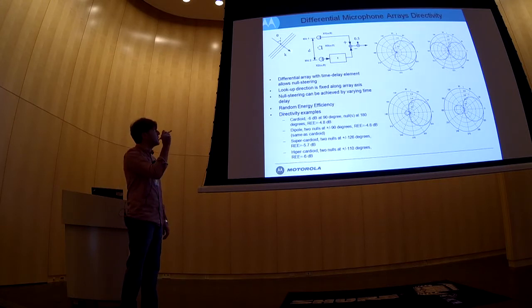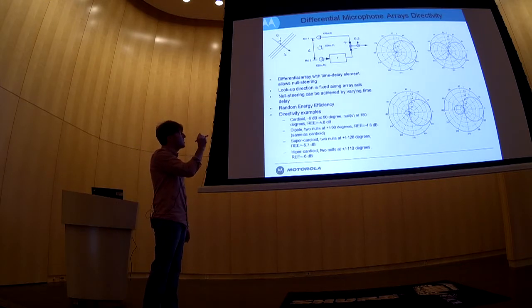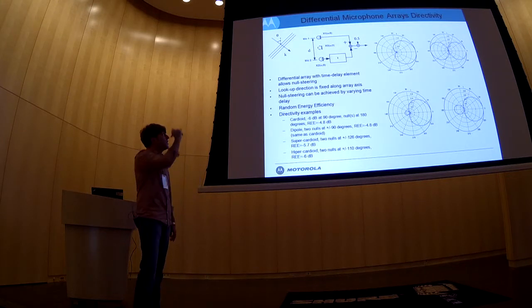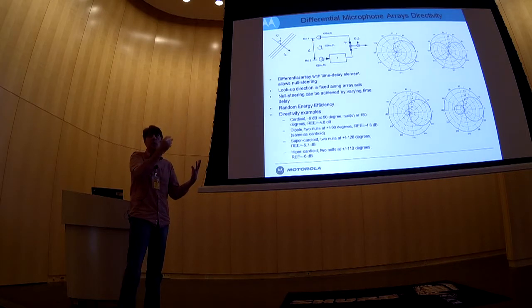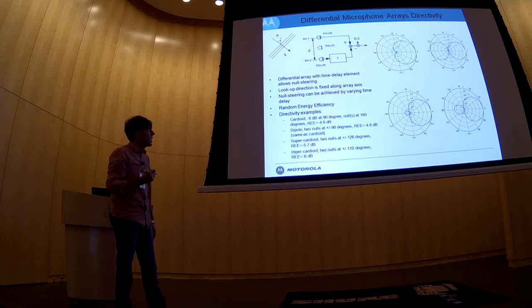And what that means is that at 90 degrees, the output of our microphone array will be 0. And one thing to notice is that this is axially symmetric. The array itself cannot differentiate whether the signal propagates from the left side or the right side, because the delays in both branches will be identical in both cases.